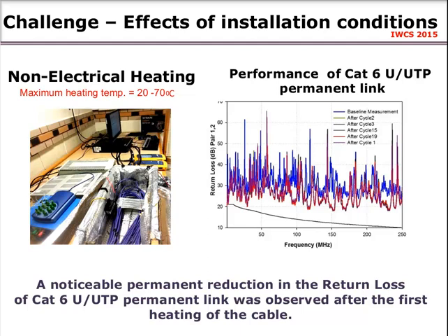The reason why we conducted this study was because in some installation environments such as stadiums, airports, and shopping malls, the local ambient temperature on the cable is not always constant. The occasional increase in user density on the network can trigger a rise in temperature on the cable. Additionally, wireless access points will be required to function in increasingly remote locations and harsh environments. So, the variation in the ambient temperature can influence the mechanical behavior of the cable.